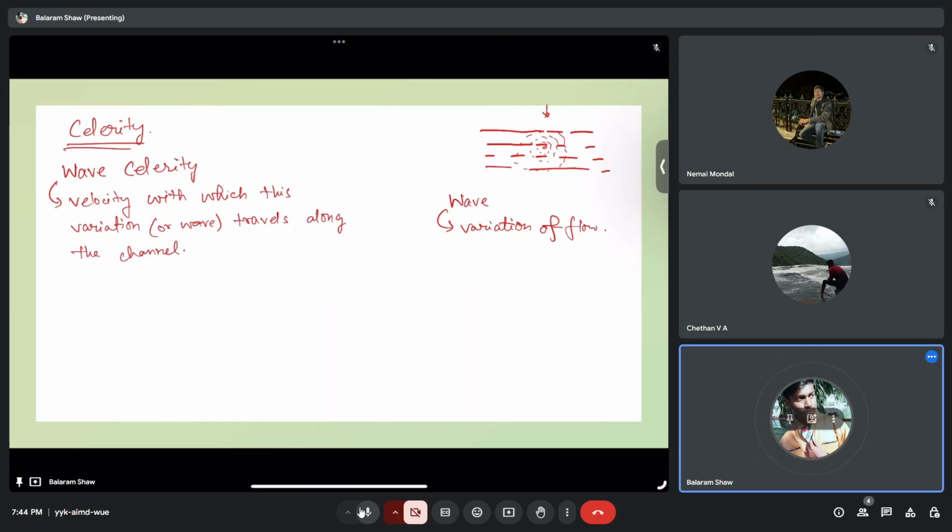This happens in the flow also if the flow is happening. Why are we talking about celerity? Because celerity is the type of variable used in a variety of hydrological models and flow routing algorithms that simulate changes in river discharge. For basin scale, it varies from 0.25 to 10 meters per second, because it is a velocity and hence the unit is meters per second.